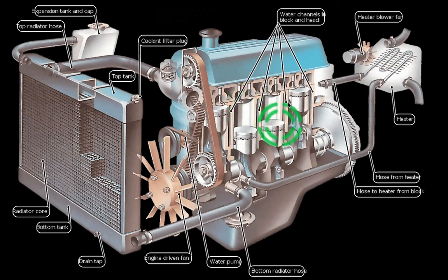Because your EGT, exhaust gas temperature, your cylinder temperature at idling remains, let's say, 250 to 300 degrees, right? But when you're stepping on it, it can go up to 700. So when you are doing like 120, let's assume you're at around 450 plus of EGT. So 450 of EGT, your cylinder temperature is gonna make this hotter than it should be.